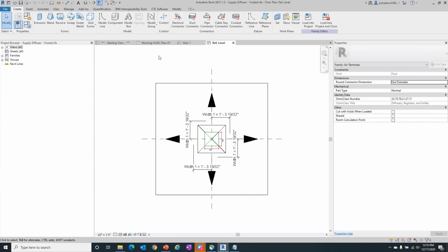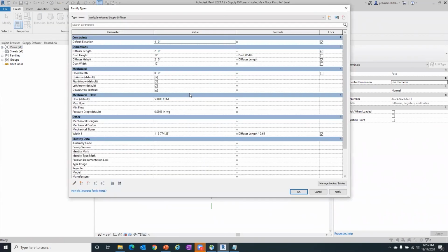So going a few steps further with a family like this, obviously we would go in and put in specific information for those parameters that we plugged in. But that is also another thing you can do in that family processor: if you have general information that you know is going to be the same for all of those, you can add it in the family processor as well. You can add those default values, which saves you even more time.